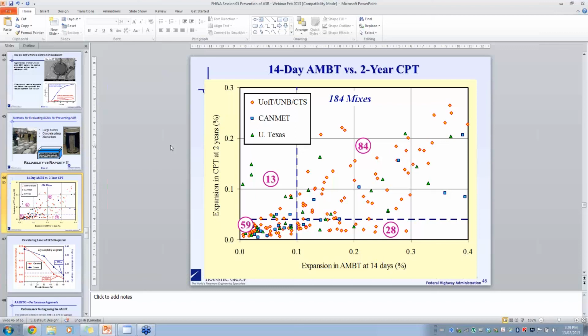And if the alkali of the pore solution drops, that's going to accelerate the release of sulfates from the calcium silicate hydrates where they're bound because of the heat curing. So ASR can often be a precursor to DEF. So I think it's always likely the ASR occurred first. The big question is determining if both of them or either of them actually occurred.